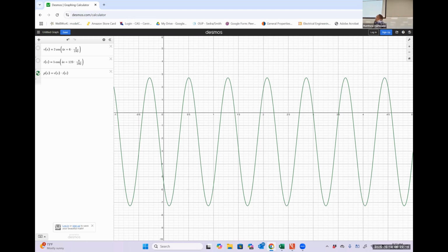This is going to happen anytime we have any energy storage elements like capacitors or inductors in our system, okay? Anytime we have temporary energy storage, we are going to see that for certain intervals of time, our load winds up supplying power back towards our source. That happens on a small scale in our homes. It happens on a much larger scale with the utility grid and all of that kind of stuff too. We'll talk about the inefficiencies related to that in class on Friday when we talk about power factor and how to correct that, okay?